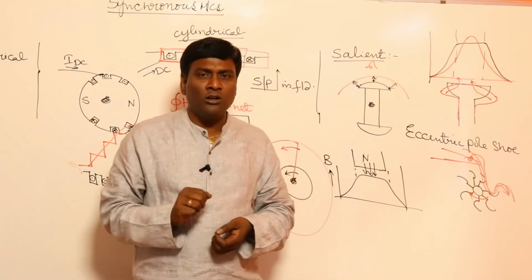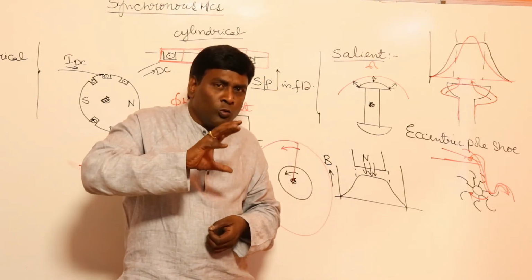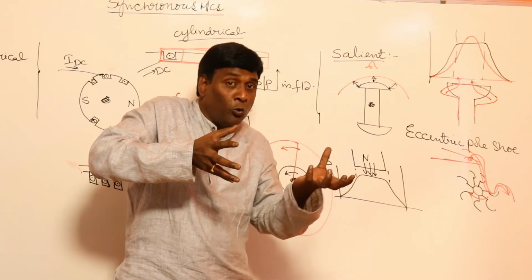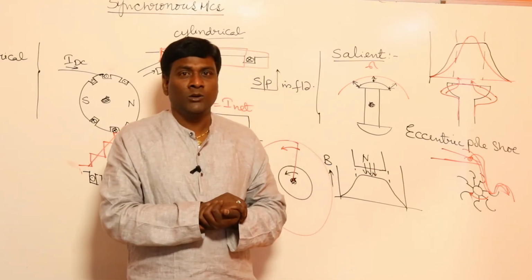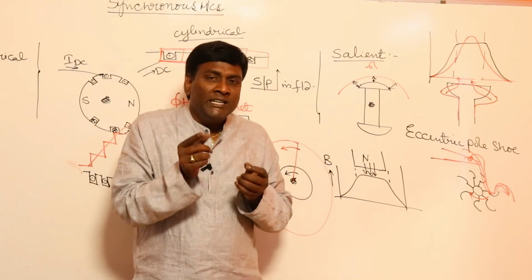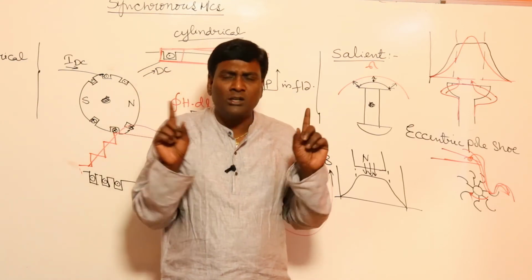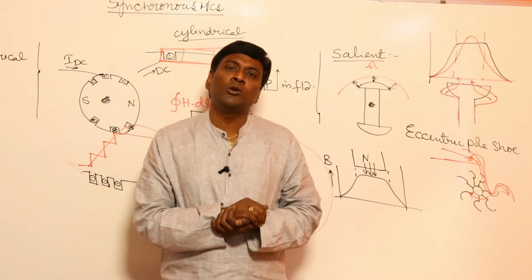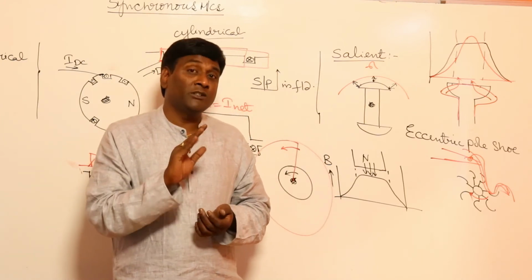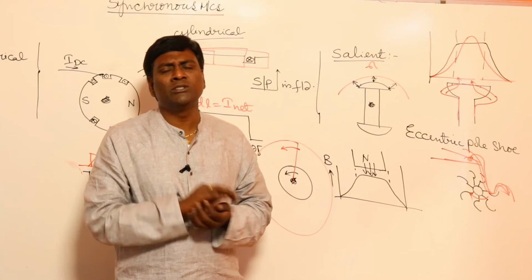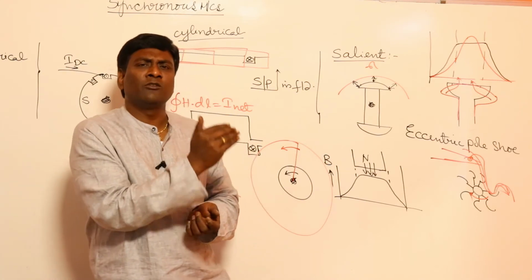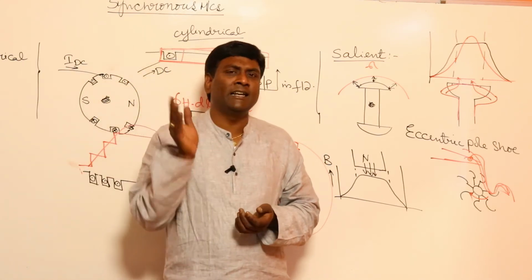In case of a motor also, the motor is trying to rotate the rotor in this direction, but the load is trying to stop me. So in a motor, what is load? If somebody is trying to stop my rotation, that is nothing but load. So in a motor or generator, mechanical stress will be more on the shaft. So the shaft is going to be the costliest part, and methodologies like cold forging should be used. It is none of our business for the time being; in detail we will see.